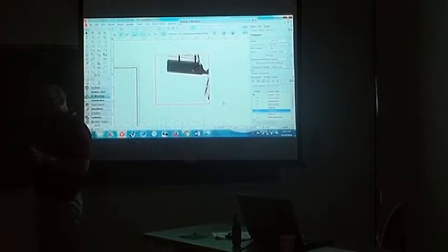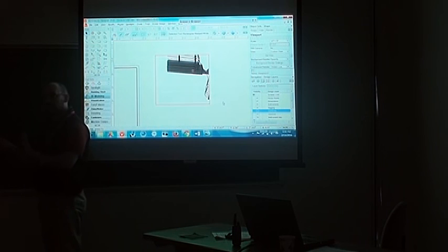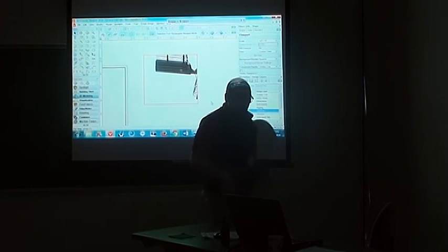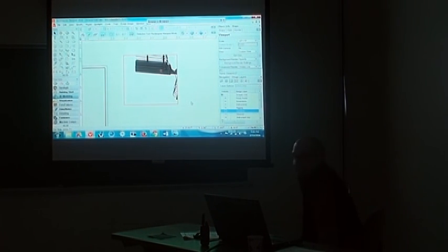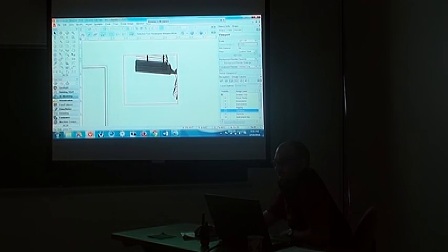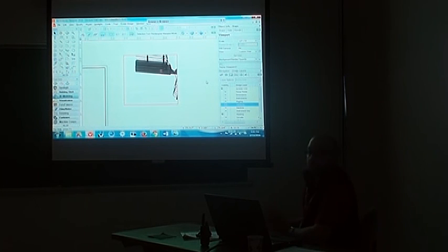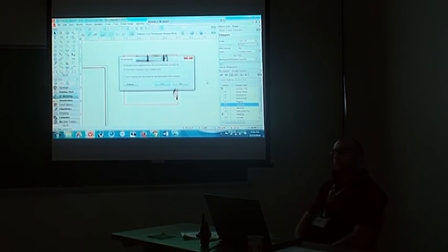So does that kind of make sense? Like how you could get to elevation drawings of parts of your model once you have it all created. Any questions? But the organizational layer names, layer and class, that's very important. Because really it allows you to, especially when you're doing this kind of intensive work in 3D, turn objects off. That is really critical.